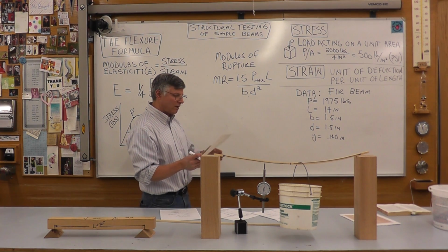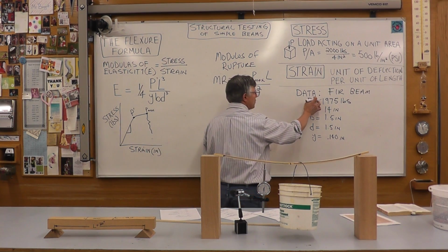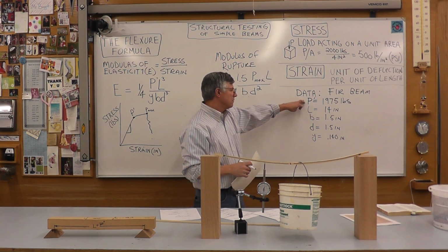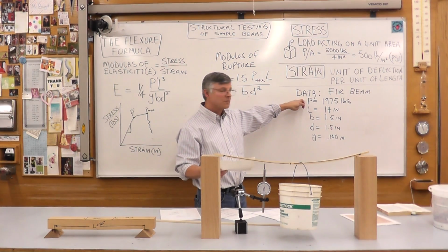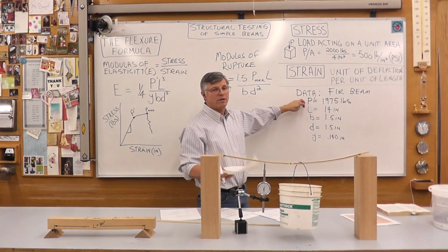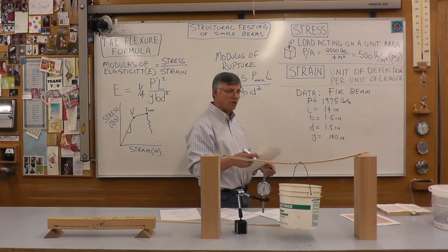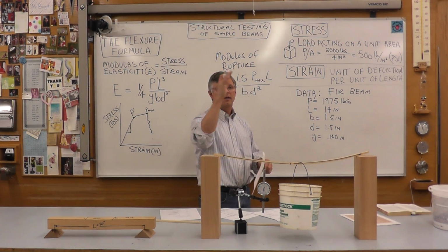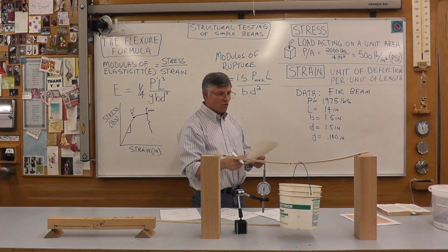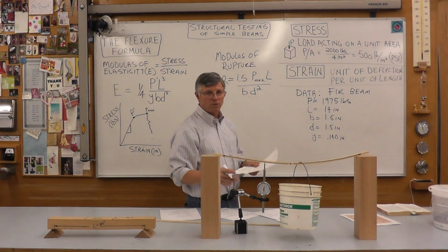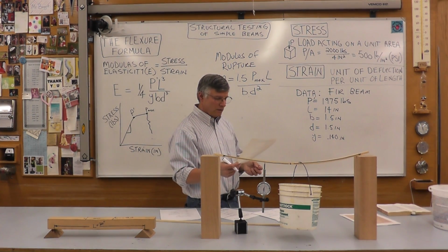So anyway, if we want to calculate the modulus of rupture, again, you plug in. Now for this, you would have to get the universal testing machine to tell you the data of when the material has reached the proportional limit, P prime. In this case it was 1975, and there are gauges, these dials on the gauge, that are recording this data for you. You won't be able to do that in this kind of simple experiment, but you could guesstimate and get pretty close.